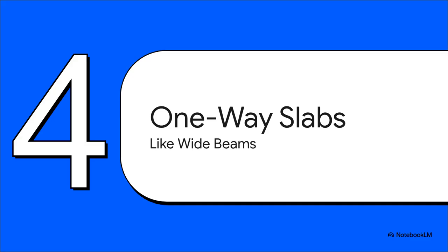Okay, let's switch gears to one-way slabs. The great news is, if you understood how we designed that beam, you're already 90% of the way to designing a one-way slab. Because, as we'll see, a one-way slab basically just acts like a really, really wide, shallow beam.